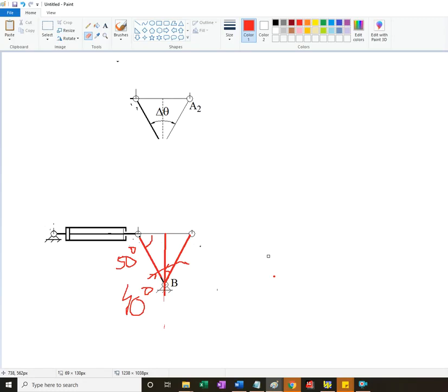And the transmission angle, by the way, let me change color. So transmission angle is going to be this one. And it's also going to be equal to, in terms of deviation from 90 degrees, this angle here, if I'm to draw down, so this is 90, this angle here, it's equal to this angle here. And then on the other position, I have transmission angle is going to be equal to this angle.